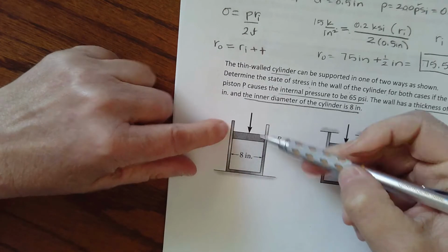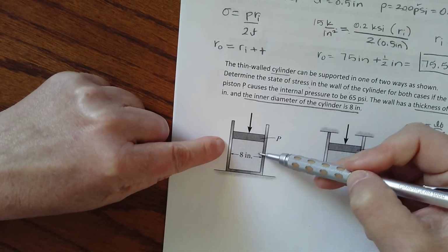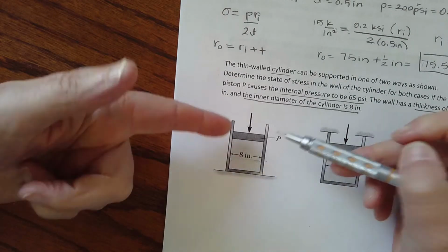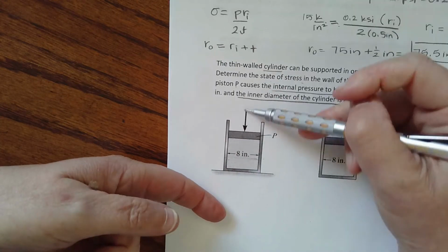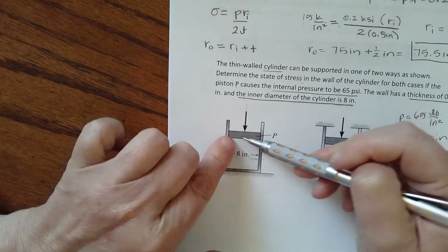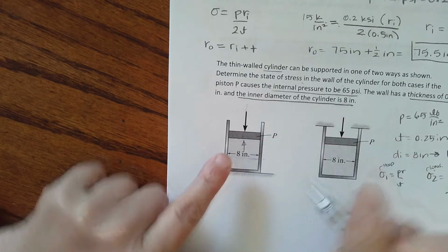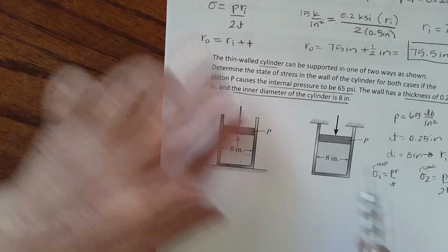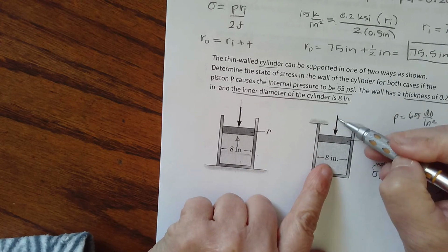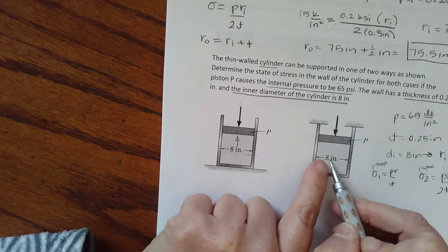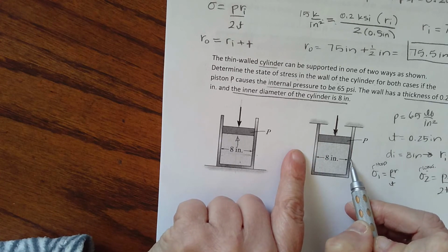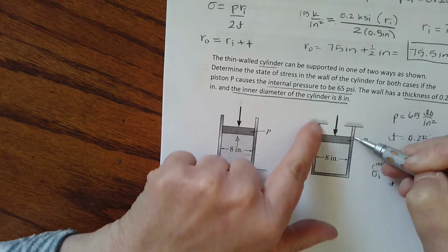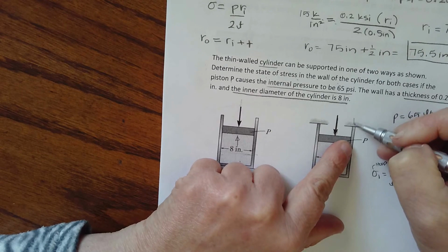Okay, in this case, as I'm pushing down, there is pressure being created. It is going to want to push out, which is going to create a hoop stress. However, these walls are not taking the longitudinal force pushing down, because the liquid is pushing back up. And so the stress in the longitudinal direction of the tank is 0. When I look over here, as I am pushing down, we are creating pressure in here and it's going to be pushing out. So that's our hoop stress. But we are now putting a force in the sidewalls, because it's being connected.